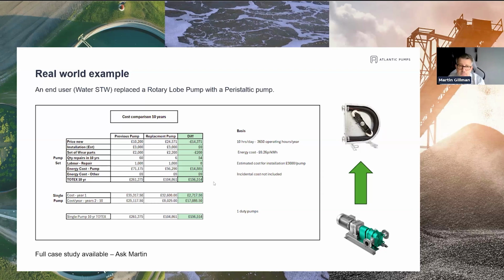So, going back to my previous slide, don't assume that because they both have a 7.5 kilowatt motor, which they do in this case, they're both using the same amount of power. They're not, absolutely not. The energy difference is, in fact, over 10 years, about £1,400 every year more to run one over the other. And that's a simple function of just how they work. A rotary lobe pump has to turn 2 shafts off one drive, 2 lobes spinning with interference fit, with resistance, in that casing.